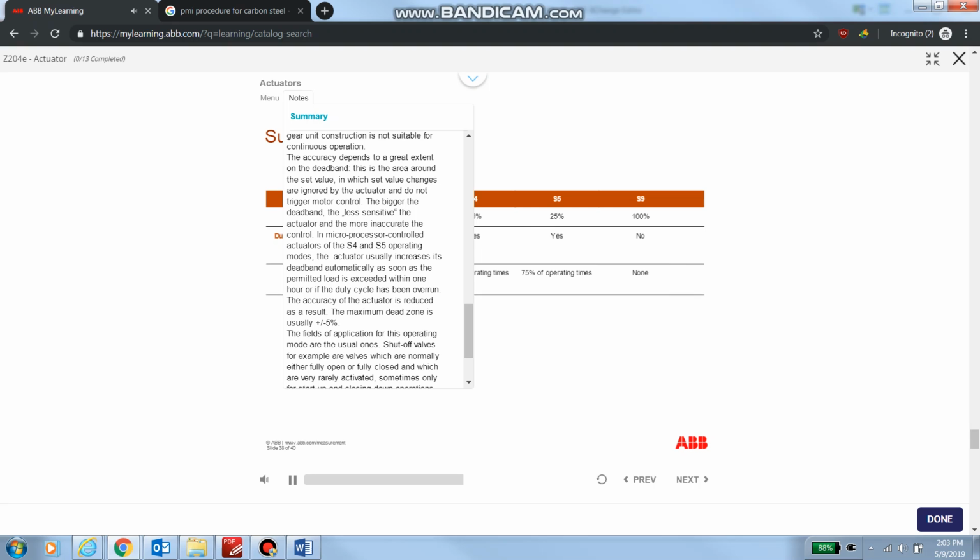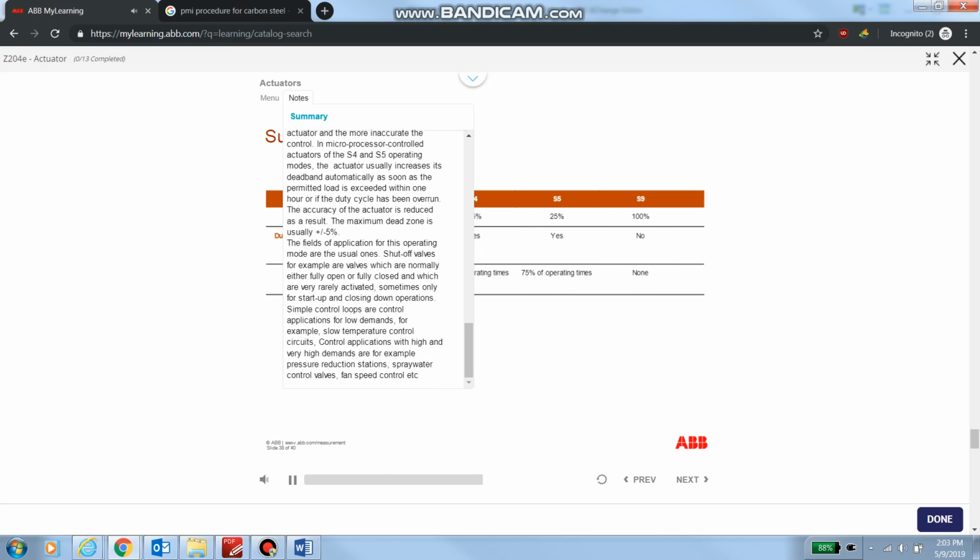The typical efficiency is the relationship of power introduced to power supplied. Ideally, the efficiency would be 100%. The total efficiency is the product of the individual efficiencies. In electrical actuators, this is, for example, the efficiency of the actuator multiplied by the efficiency of the auxiliary gear unit.